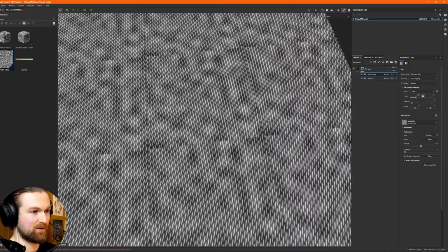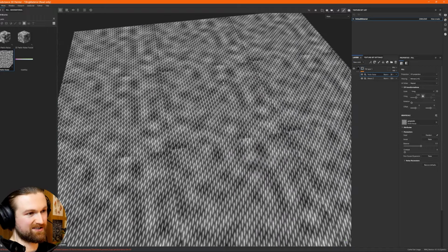And obviously if we alt click here, we can see what's happening with the mask, and it's just blotching areas and reducing that height information, maybe reducing the normal map a little bit and blurring it nicely. So the settings that I usually go for is to change this from normal to subtract, and it's barely noticeable in the mask itself. But when it comes to the main area, we can change this value and see how much it's contributing. If we put it to 100%, we can see the direction that it's going. It's just reducing the height information area. So you can pick and choose where you want this.